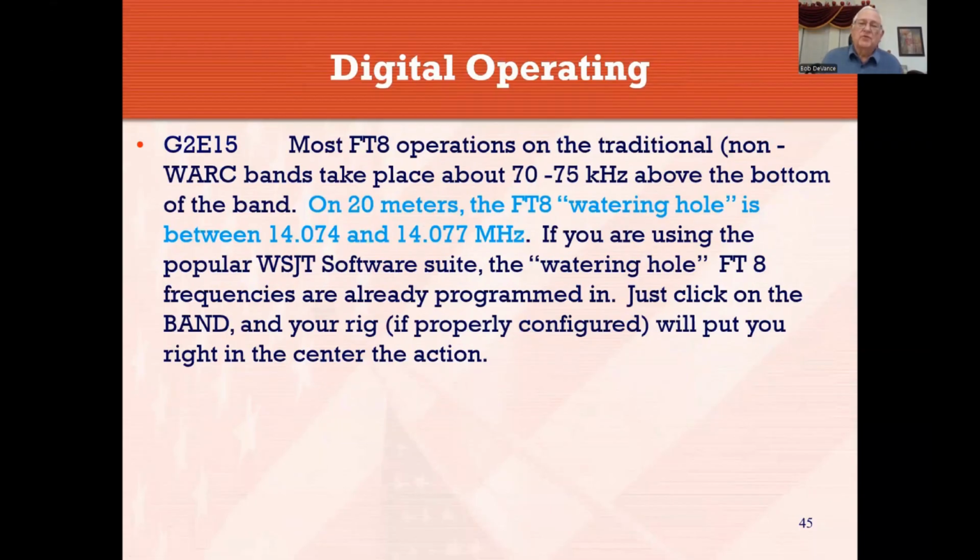FT8 operations on the traditional non-WARC bands take place about 70 to 75 kilohertz from the bottom of the band. On 20 meters, FT8 is the place where you'll see most of the activity, between 14.074. You remember 14.070 was PSK. And here we run between 14.074 and 14.077 for FT8.